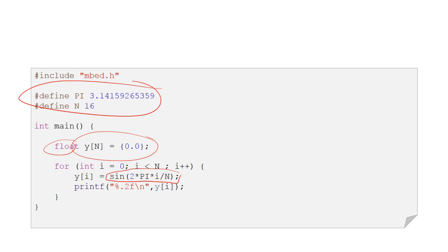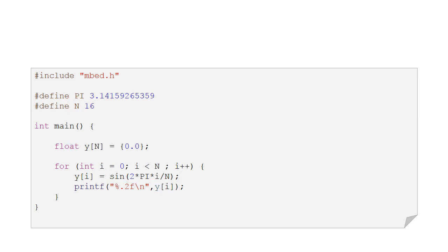It's also got this printf so we can debug and print messages. After we've done this, we've only had to do 16 sine calculations, and we can just store the values in y, and later on use the values stored in y in the DAC.